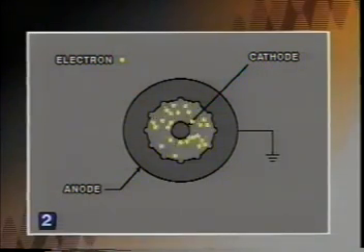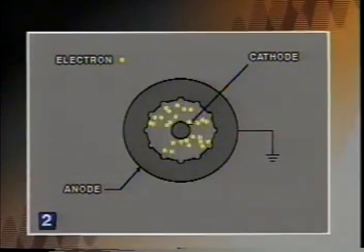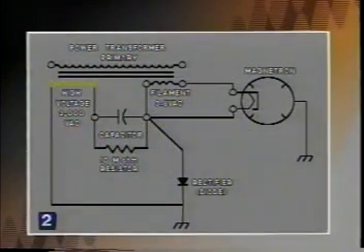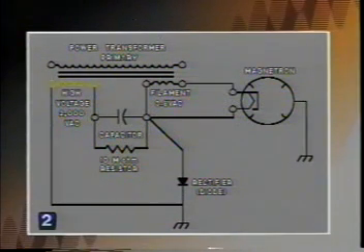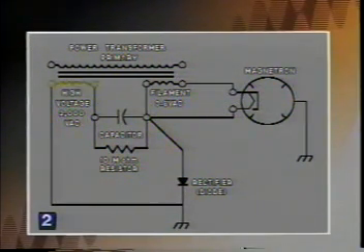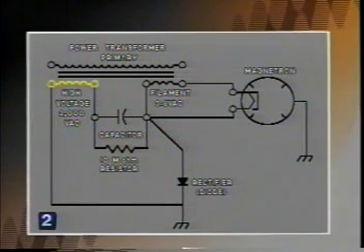If no further voltage is applied, the electrons will remain free-floating since the filament switches between the positive and negative charges of the alternating current. The other secondary winding steps the voltage up to 2,000 volts of alternating current. But even this much voltage cannot overcome the natural resistance within the magnetron. Twice that amount of power is necessary.